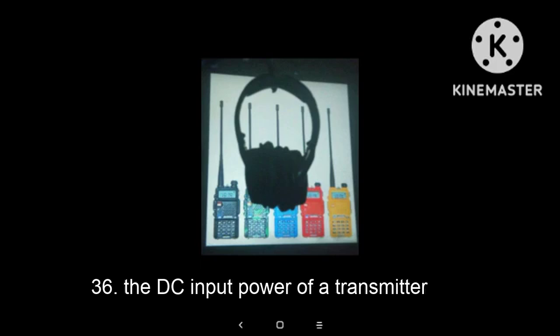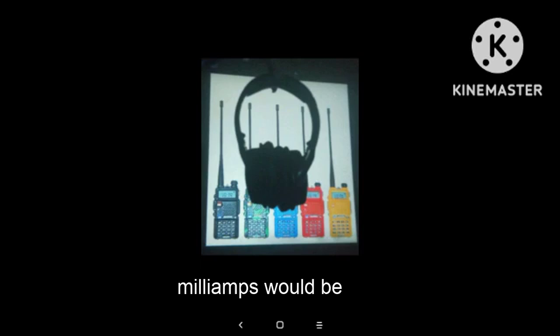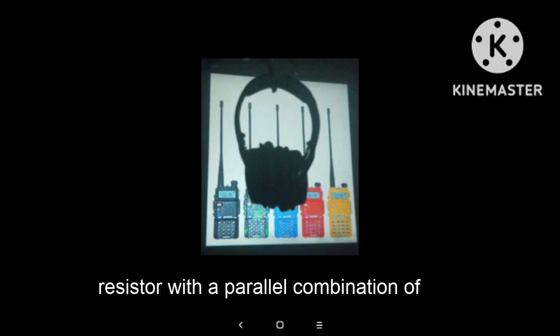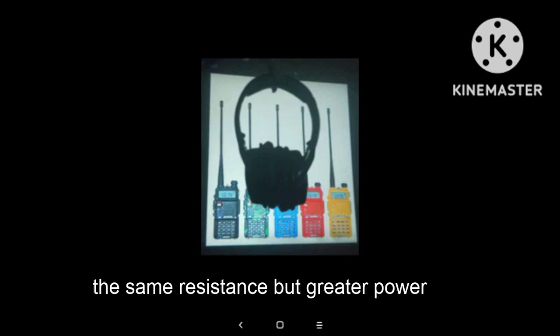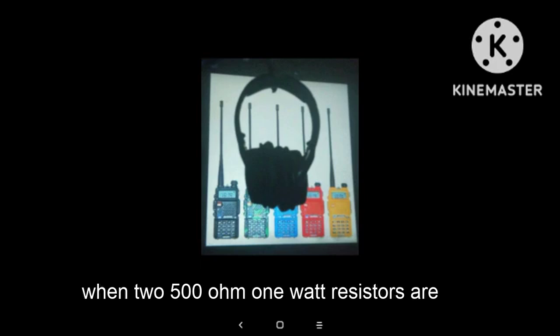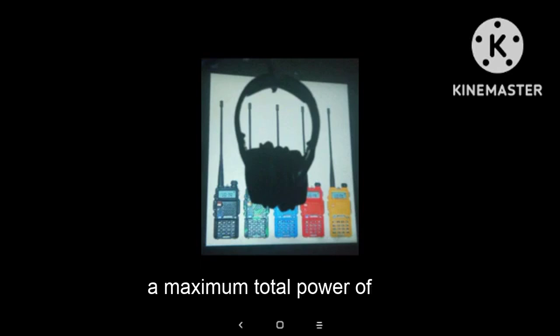36. The DC input power of a transmitter operating at 12 volts and drawing 500 milliamps would be 6 watts. 37. One advantage of replacing a 50 ohm resistor with a parallel combination of two similarly rated 100 ohm resistors is that the parallel combination will have the same resistance but greater power rating. 38. When two 500 ohm 1 watt resistors are connected in parallel, they can dissipate a maximum total power of 2 watts.